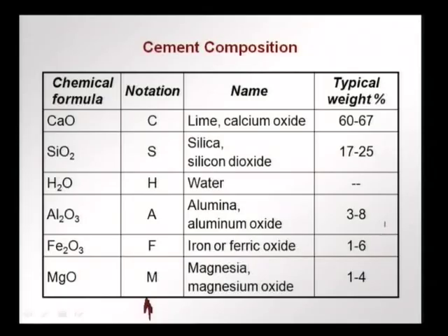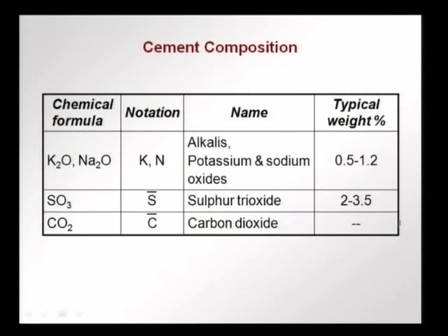setting behavior when ettringite and monosulfoaluminate are formed, and the alkalis which are present, potassium and sodium oxides, can affect the alkali aggregate reactivity, alkali carbonate reactivity, and also to some extent how superplasticizers are effective in concrete. So, even the minor compounds have some roles to play in the hydration and behavior of the cement concrete.